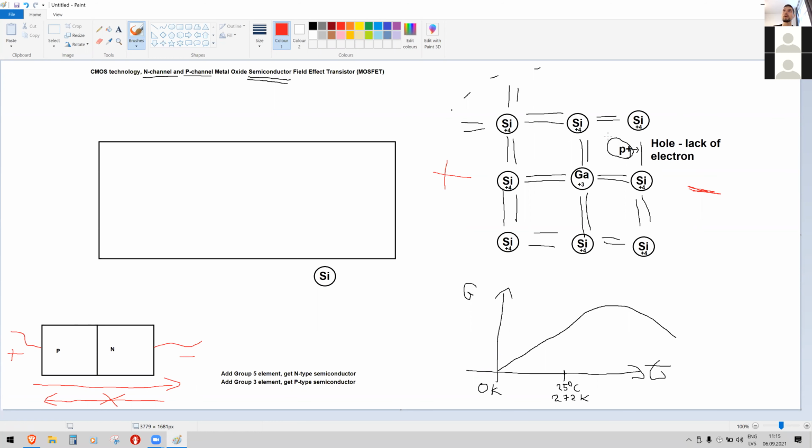Why? As I mentioned, holes and electrons recombine and all electrons are caught by all holes. There's no free carrier running around. So this region where they meet, it basically becomes total insulator. So if you put more holes in this P region, they are not compensated by the electrons and the electricity can start to flow again.